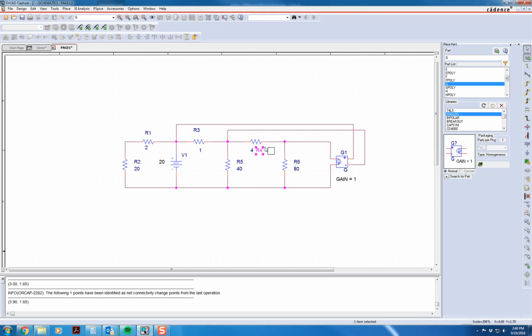So now we need a current controlled voltage source. Now this one's going to be even more challenging to set up. What we've basically done is we've wired this up in parallel, because we know things in parallel to that 1 ohm resistor have the same voltage. Awesome. Now we need the current controlled voltage source, and that would be H here.